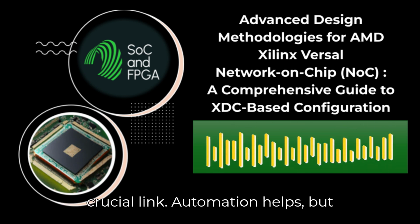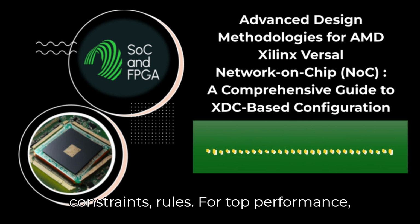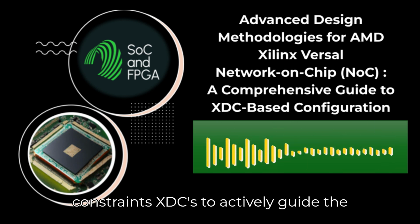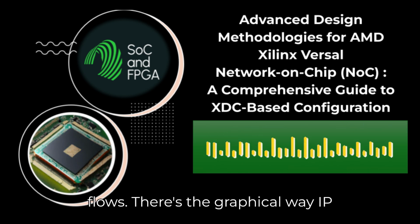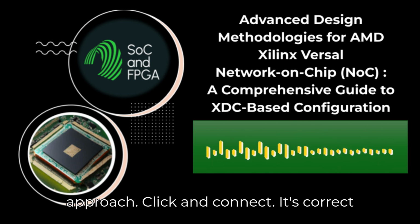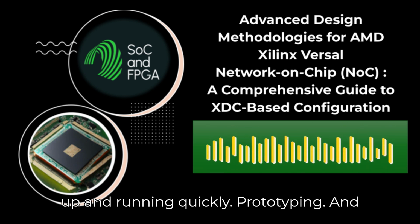Automation helps, but physical reality, defined by your constraints, rules. For top performance, you have to use Xilinx Design Constraints, XDCs, to actively guide the compiler. Tell it the physical realities you need. Which brings us to the design flows. There's the graphical way, IP integrator, IPI. Yep, the block diagram approach, click and connect. It's correct by construction, great for getting things up and running quickly.